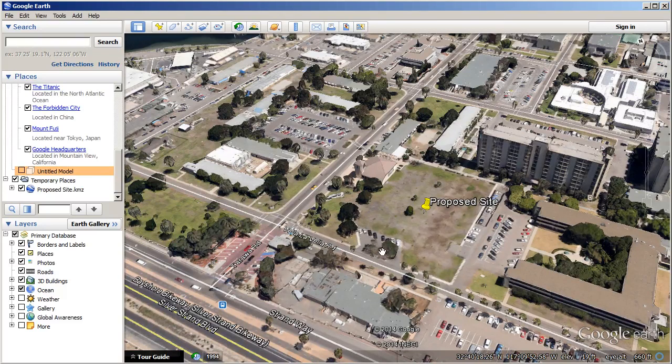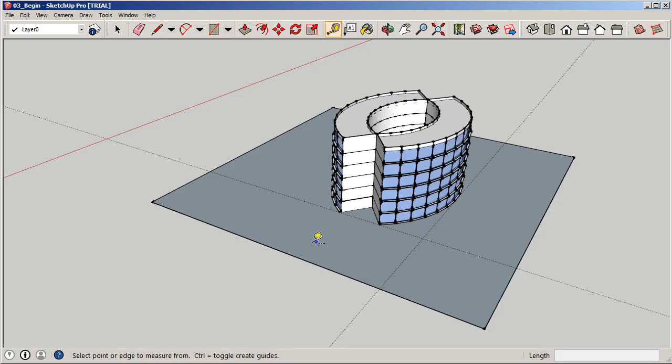We're also going to have 45-degree parking here as well as on this side. So what that means is we're going to go with depth of 20 feet inward as far as the depth of this parking space. And it'll start to make sense to you here once we start laying it out. So let's jump back. So now let's lay in those measurements.